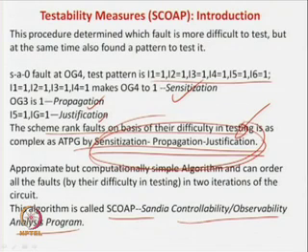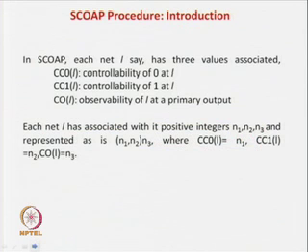It does not require going for sensitize, propagate and justify. All it will do is scan the circuit and approximately tell you which faults are easier to test and which are difficult to test, though the result may be approximate. But it can give you a clear idea of which are easier, so you try those randomly, and which are difficult, so you go for sensitize, propagate and justify. So, now we will study this algorithm in detail.